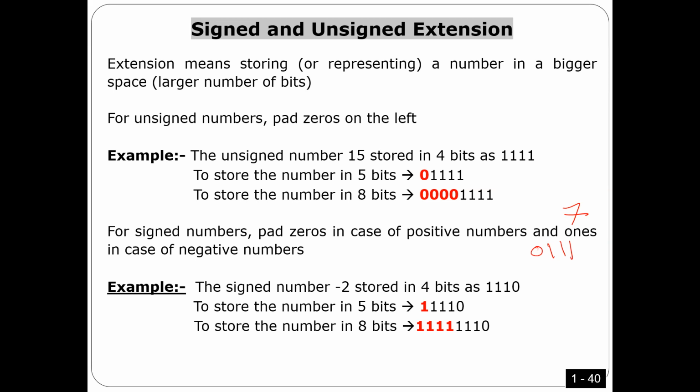That's why in 3130, you are not going to be given 2 instructions, addition for signed and addition for unsigned. No, you are going to take only 1 instruction, addition. But it works for both cases. That's why people like the 2's complement. But when it comes to multiplication and division, we're going to know multiplication, you have signed and unsigned. Division, you have signed or unsigned. Okay? Anyway, let's come to my point here.